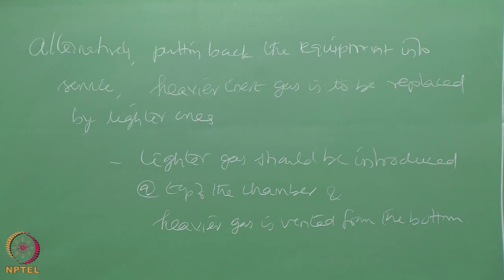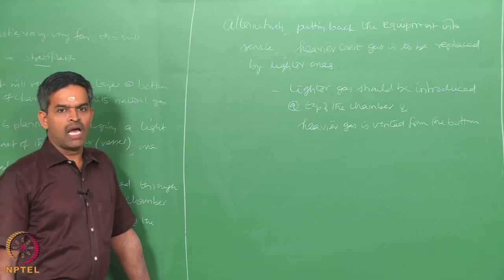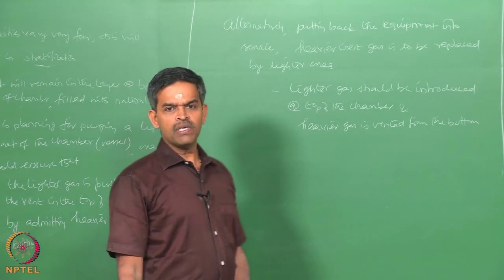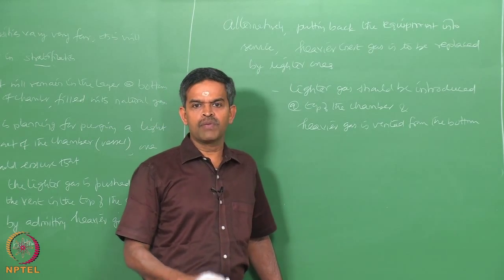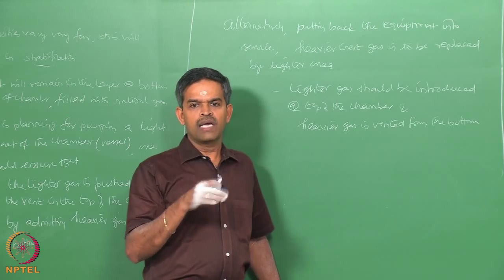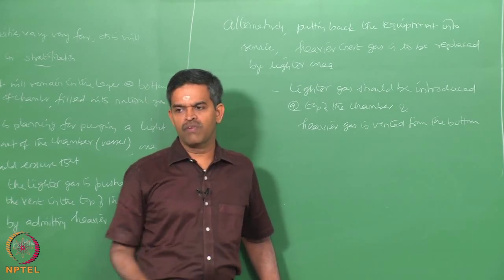When purging facilities out of service that have contained gases with higher specific gravity, then vapors can be effectively replaced with a minimum of mixing by introducing an inert gas at the top of the chamber and displacing the vapor through the bottom vents.